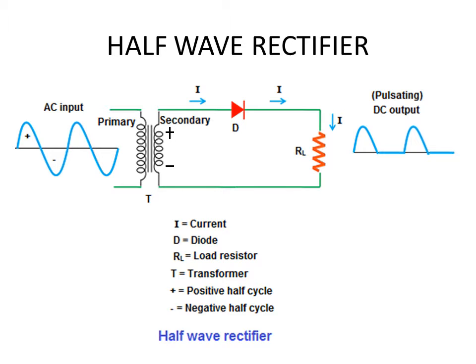The input to the voltage rectifier is the voltage appearing across the secondary of this transformer. If you examine the left part of this diagram, you begin with a wave which is the input to the whole device, and this AC is going into the primary of a transformer, and it is making a step down process there. You can see the number of turns in the primary is more than the number of turns in the secondary, so essentially this is a step down transformer.